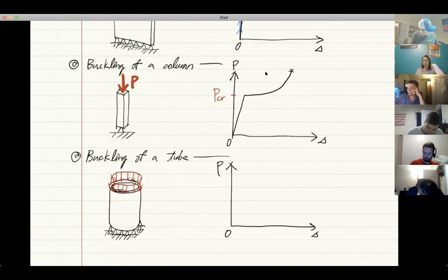First, it's going to exhibit some horizontal behavior, deflection. There's always this part in reality. The structure is going to deform anyway. But after reaching the critical load, PCR, you would jump to another point, which corresponds to a much lower force. And this jump is what we call snap-through buckling. So this will happen very, very fast.